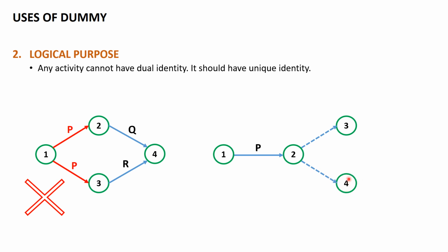So this is very important to keep in mind that whenever there is a split of an activity using the dummy, it doesn't mean that the resources and the duration will be split. Whatever is the resource consumed or the duration consumed by the predecessor activity before the use of dummy, the same value will be moved through these dummies.